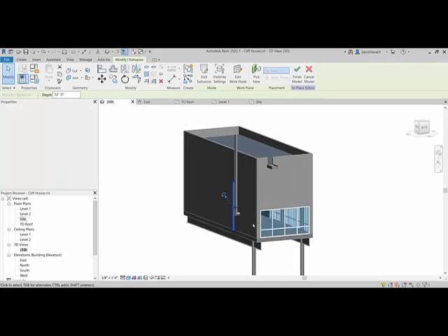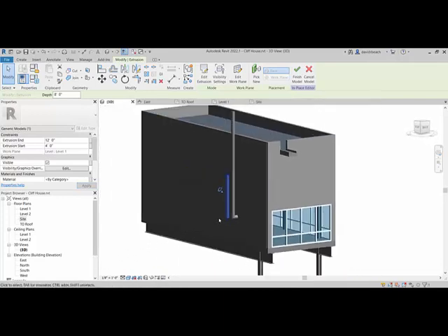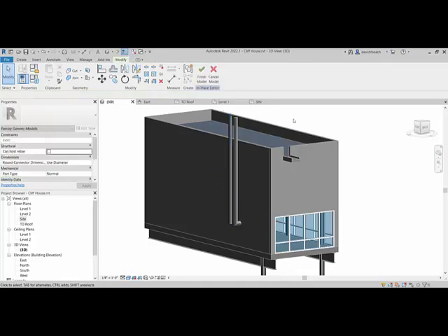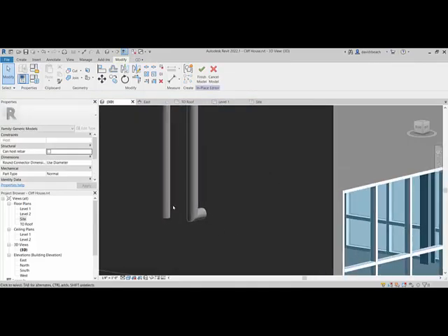I know that this is actually starting up closer to about 6 feet. So I could change my extrusion start to 6, maybe 4. 4, there we go. 4, and then that one goes up to like right about there. Right, so I'm just sort of pulling those elements up and down. Now, that doesn't have the connection to the wall though, right? So that's one more piece that I need to build in this case, which brings us to another way to look at how things like this can happen.